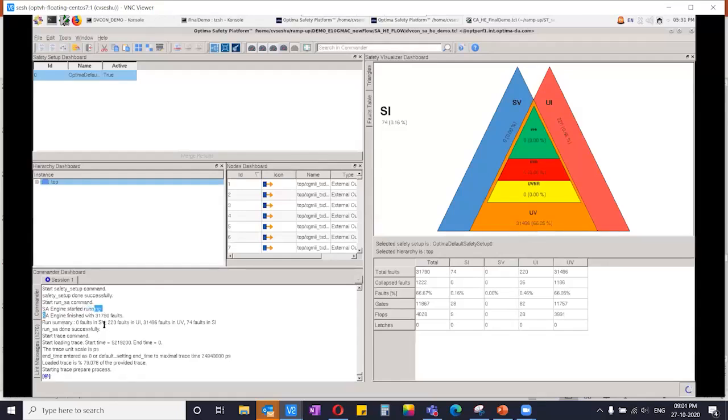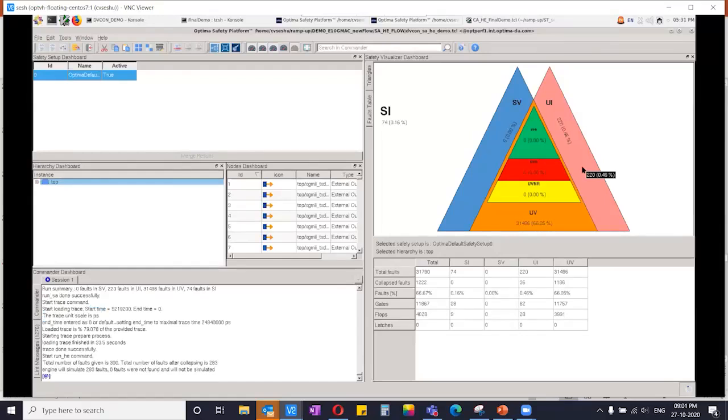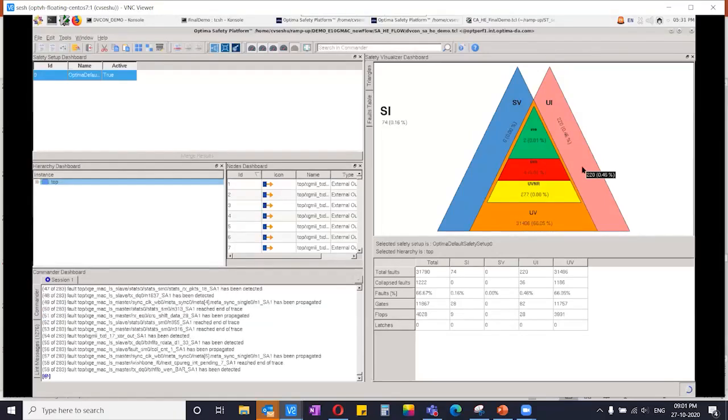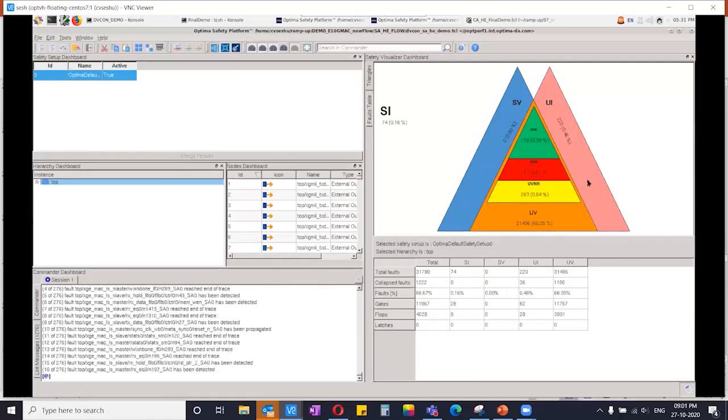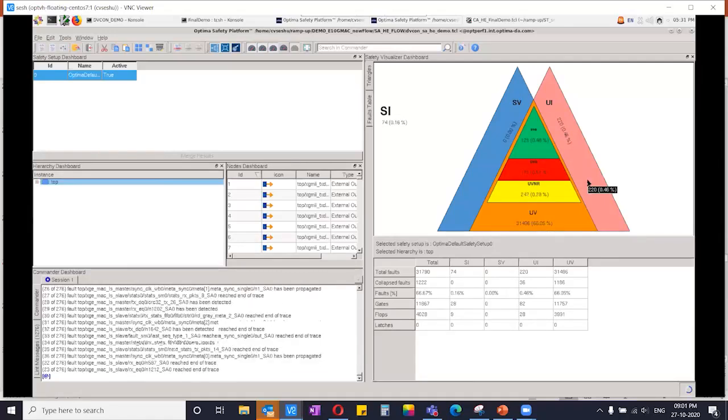Static analysis is finished, and static analysis has decided this is the segregation. There are 220 faults still which don't have a safety mechanism. Like we said, any designer should look into this first, because if a fault occurs, there is no safety mechanism to take care of it, right? So you need to go define it. Assuming that you're running the first cut SEA and HE for the first time, we don't try to fix it here in this demo, but move ahead to the hard error analysis as well.